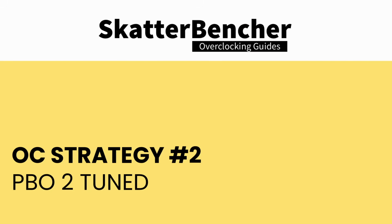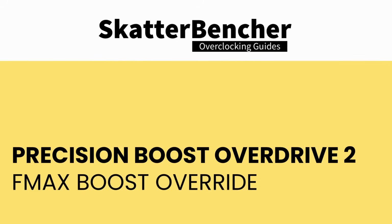In our second overclocking strategy, we tune the Precision Boost frequency curve using some of the tools available in AMD's Precision Boost Overdrive 2. Fused maximum frequency, or Fmax, is one of those frequency limiters affecting the Precision Boost algorithm.